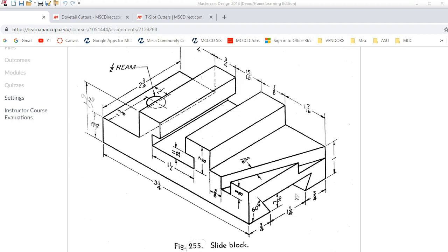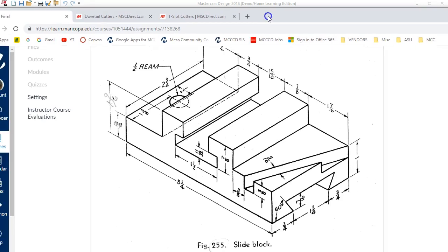We're also going to need to set up a T-slot, and since we're setting up tools, we'll go ahead and create a thread mill, single point thread mill, and then probably come back and, while we're going through that process, do a multi-point if you are picking a specific thread to thread mill. All right, and then in the process, we'll go ahead and set up a tool library so we can reuse those tool geometries for our process.